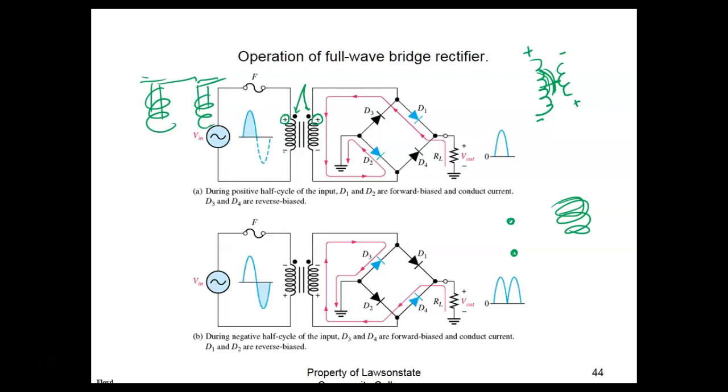Regular transformers, we don't care. Like I said, because when we rectify it to DC, it doesn't make any difference the relationship between your primary and your secondary. We're looking at the polarities on the secondary. We're not worried about the primary, and then our diodes are used to steer it around. So that's what those dots are up there, by the way. And that's why instead, they can put plus and minus. Normally, what I do is I ignore the primary and I just come over here and put it on the secondary.